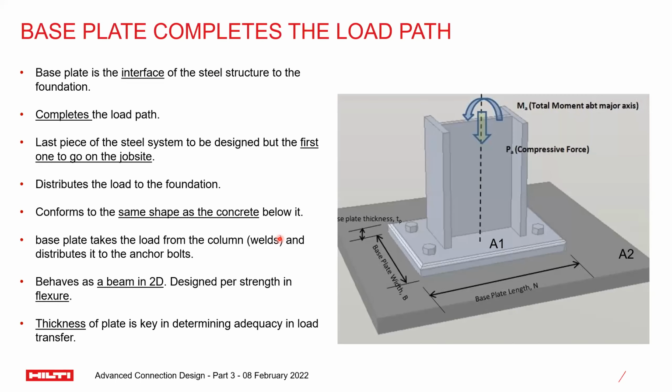Okay, so why do we need a base plate, or what is its purpose? The base plate completes the load path. That's one thing. It usually can get overlooked in many scenarios because I've heard the term, "it's just an anchor anyhow, right? It just holds a place." But actually it's not. It literally is a node that you need to calculate in all of your calculations, to transfer your loads.